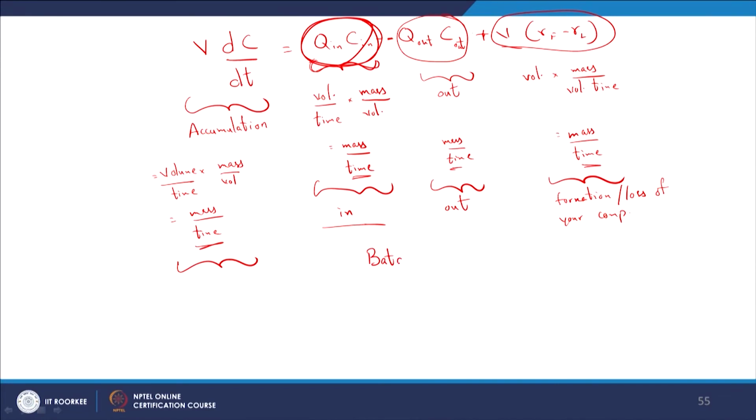So, I believe we are almost out of time. So, let us quickly review what we discussed. So, we discussed batch reactors, plug flow reactors and continuously stirred tank reactors. Batch reactors are usually used in the lab, plug flow again in the lab or engineered systems or natural systems like rivers, CSTR either lakes, right, or most of your ASP or most of your unit processes, right. And for all these cases we looked at the relevant conditions, how to describe them, and then we looked at the fundamental mass balance equation, and then looked at the generic equation we are going to use throughout the class.